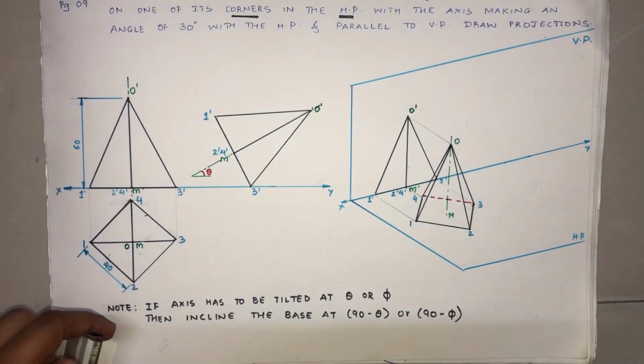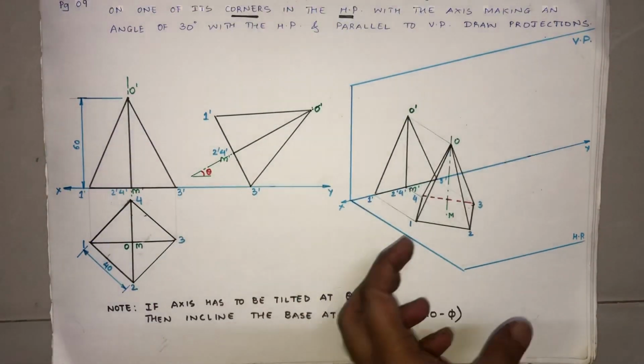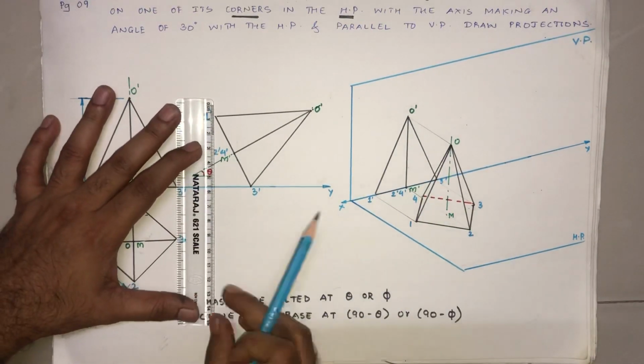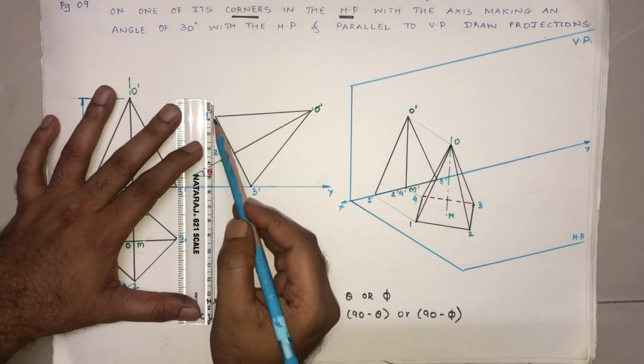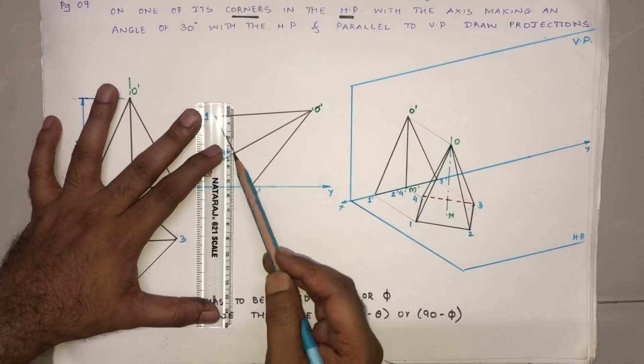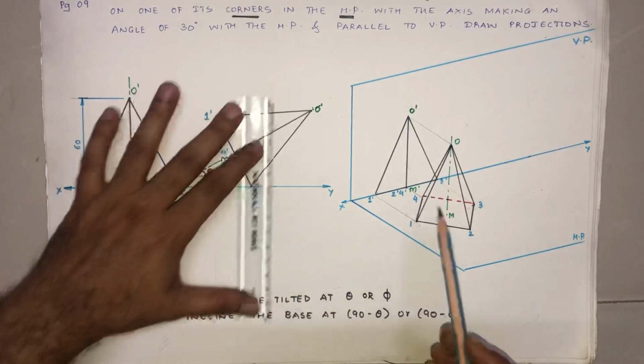Now, by tilting this view, we have tilted the solid. On tilting the solid, this is the way you're going to complete the top view. That is the final stage. I'm going to project all these points below. You can see I'm using construction lines, absolutely light lines.